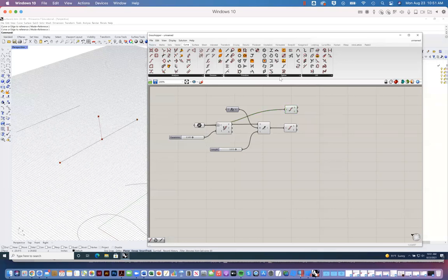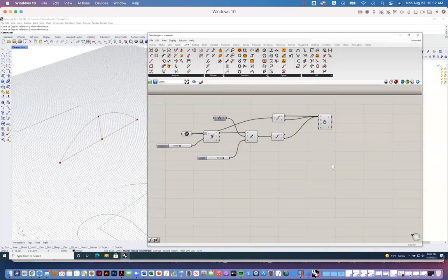Now I'm going to draw a curve of my own. I'm going to make a NURBS curve. No, you know what? I'm going to make an interpolated NURBS curve. There we go, interpolate. I'm going to plug in this as a vertex, and this is a vertex, and this is a vertex. So we have those three vertices, and now I've made this sort of bow, right? So now I have this curve, and I have this curve, at the top and bottom of my truss.